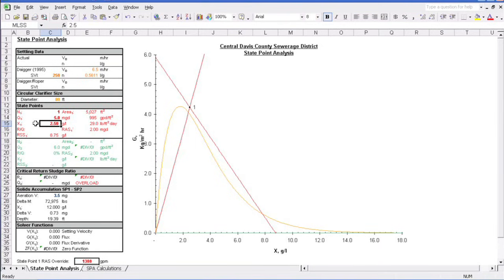In this case, if the mixed liquor concentration was preemptively reduced to 2.2 grams per liter, we see that we'd be back in the safe shelter of the settling curve. However, this is not a realistic approach to dealing with unexpected high flow events that occur from time to time. Typically, the only other option available in this scenario is dosing your RAS line with some chlorine. A quick dose of chlorine in the RAS can attack the filamentous bacteria and lower the SVI. If the chlorine dose was able to drop the SVI down to 200, we'd find ourselves back in the safe zone. However, this option is only available to treatment facilities with the proper equipment installed.